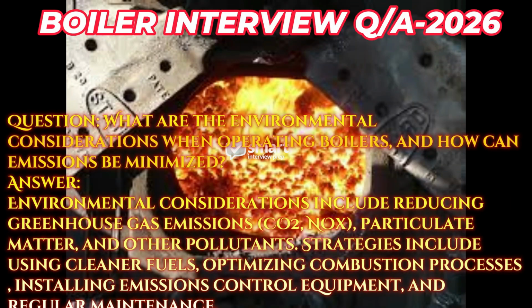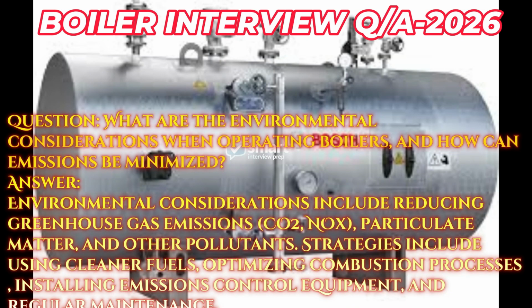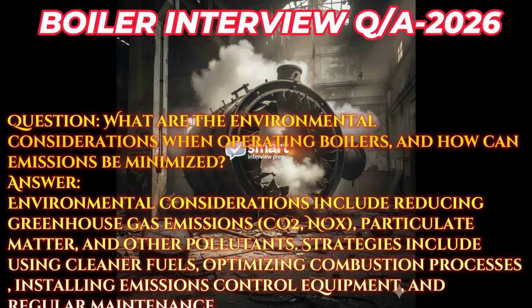Question. What are the environmental considerations when operating boilers, and how can emissions be minimized? Answer. Environmental considerations include reducing greenhouse gas emissions, CO2, NOx, particulate matter, and other pollutants. Strategies include using cleaner fuels, optimizing combustion processes, installing emissions control equipment, and regular maintenance.